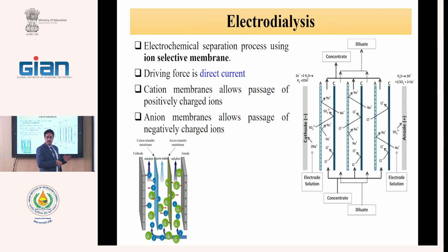When you see electrodialysis, you see only two electrodes, two metals, very compact. But in this area, in this 2 centimeters, we have 10 membranes, and the distance between the membranes is 1 millimeter. Why is it so near? Because we reduce the electrical resistance. We reduce the ohm.